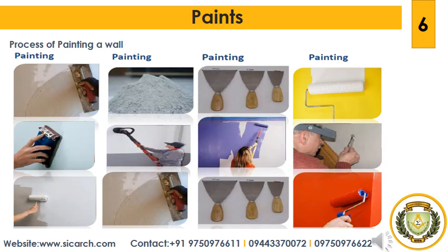The advantages of spray painting are that the speed of the work increases considerably. An experienced painter can create artistic patterns or designs on the surface by spraying paints of different shades. It is found to be economical in material and labor. 2 coats of spray would suffice, whereas ordinary brush painting would require 3 to 4 coats. Since mechanical equipment is used, the paint remains always in a state of motion. This ensures uniform mixing of the ingredients of the paint.